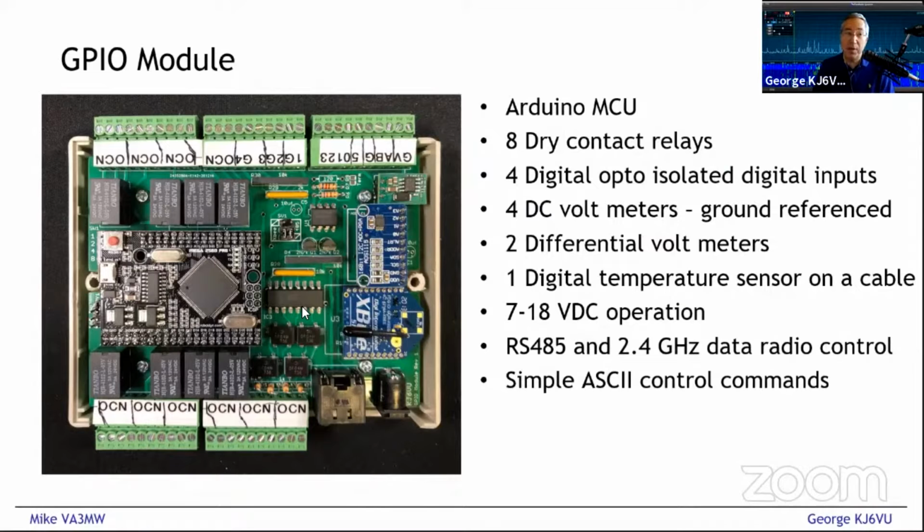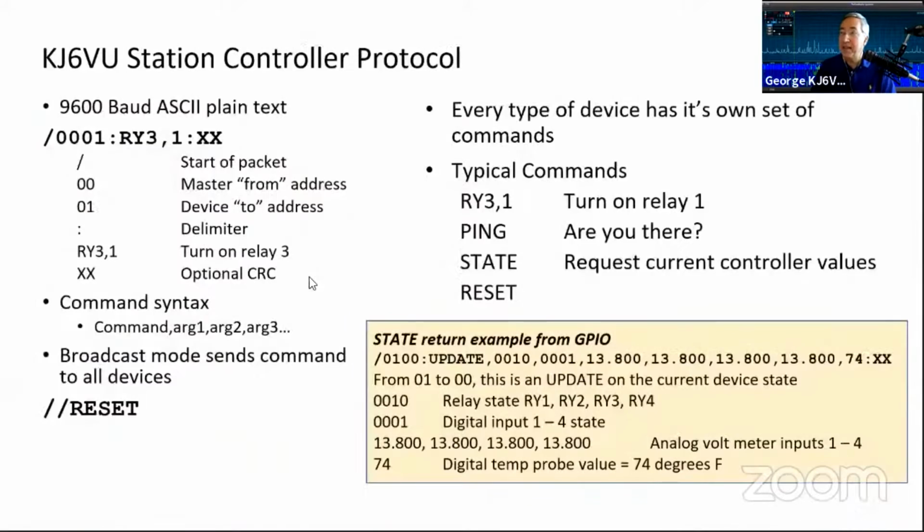So also, by the way, one big safety tip is don't use linear regulators on something like this. Use a little switcher. So the tiny little green circuit board in the upper left-hand corner is a 5-volt 1-amp switching power supply, which allows you to shove 13.8 volts into this, and it'll never get warm. If you put in a traditional 7805 linear regulator, it'll get hot. So go with a switcher.